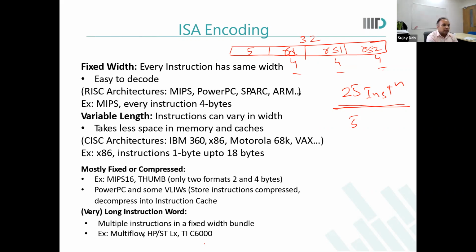But you will see that to do most things, you also need to deal with immediate values, and for that you will need some additional bits. So what I'm trying to say is I can have fixed fields in my 32 bits for each of these: destination register field, first source, second source, and immediate value, etc. Now, if I have this fixed for all instructions, then my hardware becomes much simpler, because to identify which instruction it is, I just have to read the first 5 bits.